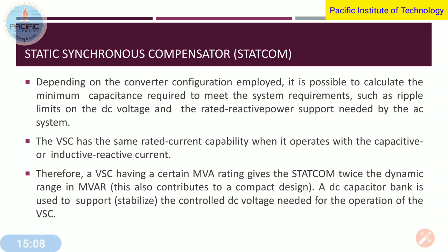Now, based on the converter configuration, it is possible to calculate the minimum capacitance required to meet the system requirement. And what are the requirements? The requirements are ripple limits in the DC voltage and the rated reactive power support needed by the AC system. So based on these two requirements, we can design the minimum capacitance for the STATCOM.